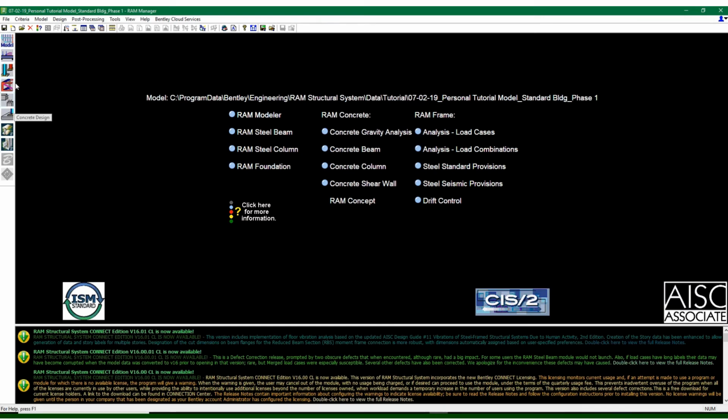And this is where we get into the settings for P-delta analysis, which is a structural stability analysis and design. P large delta, P small delta is all taken into consideration at this location. Various things like the diaphragm settings are taken into consideration in RAM Frame.